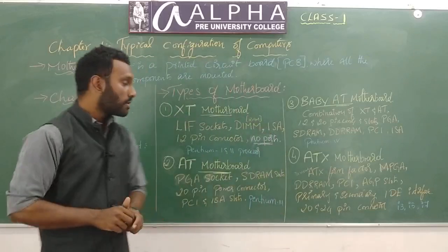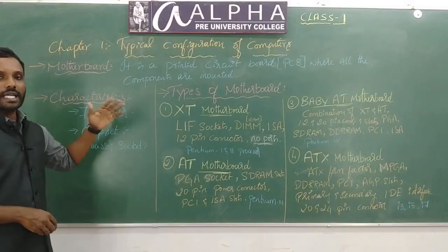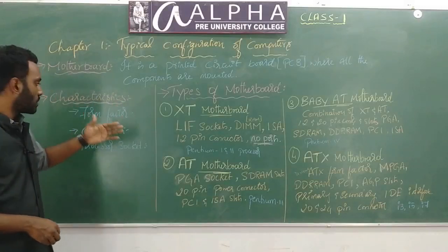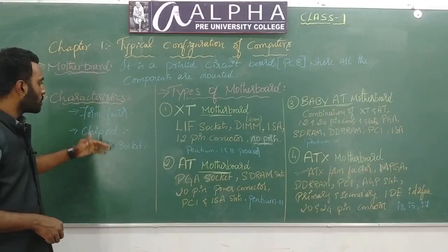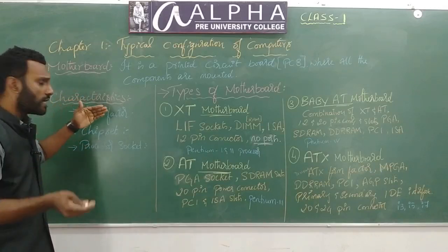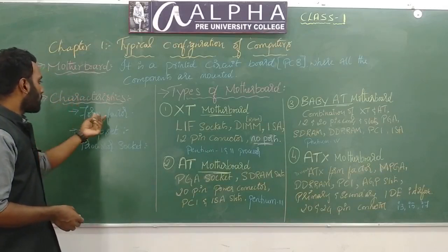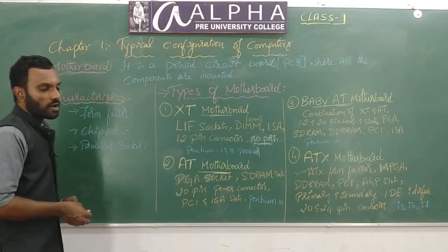Next, the characteristics of a motherboard can be defined by these three things: form factor, chipset, and processor socket. What is a form factor?